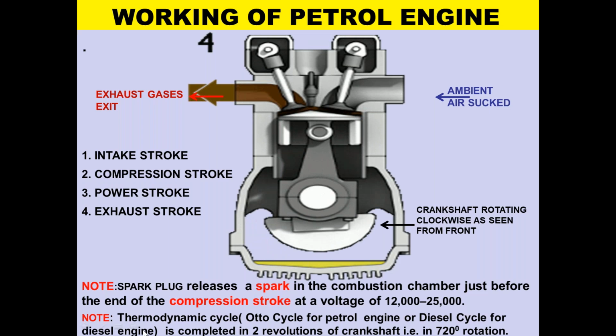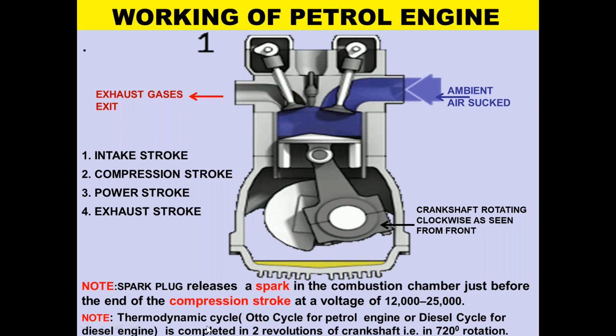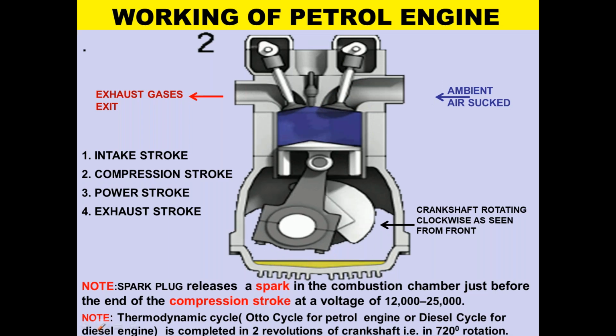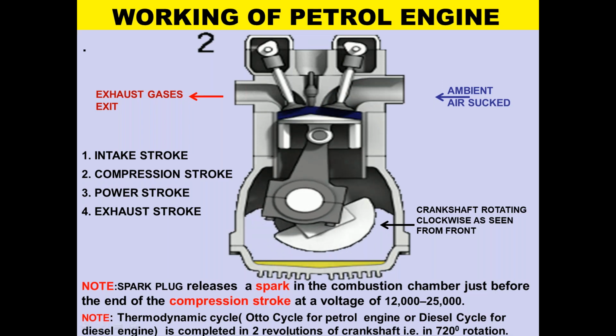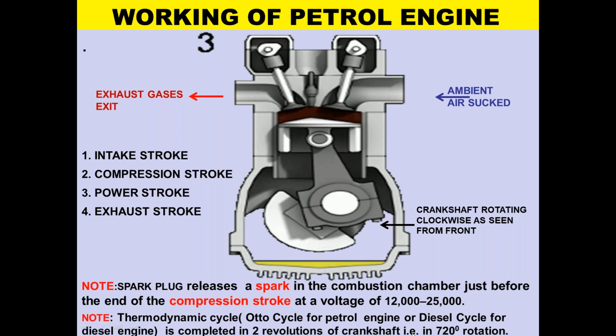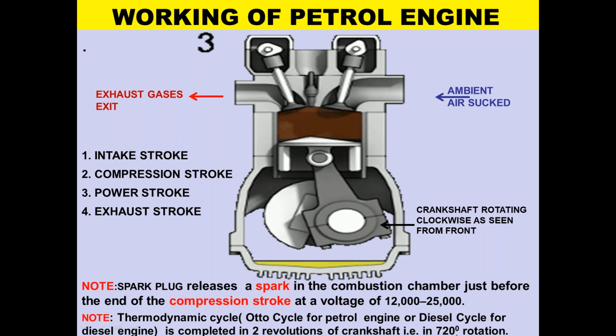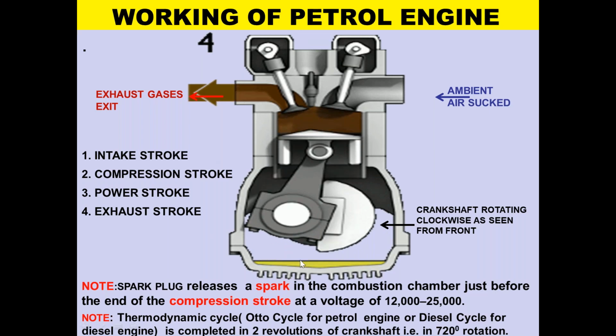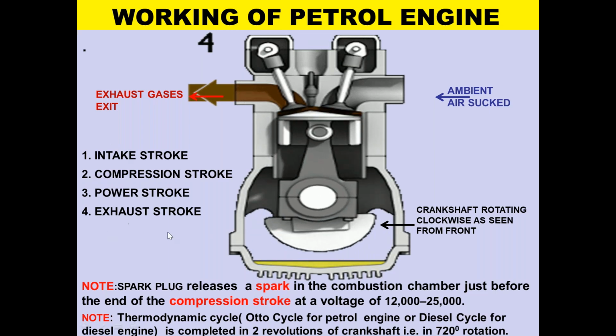Again, please note that the thermodynamic cycle, that means Otto cycle for petrol engine or diesel cycle for diesel engine, is completed in 2 revolutions of crankshaft, that is in 720 degree rotation. One thermodynamic cycle is completed, or the 4 strokes are completed.